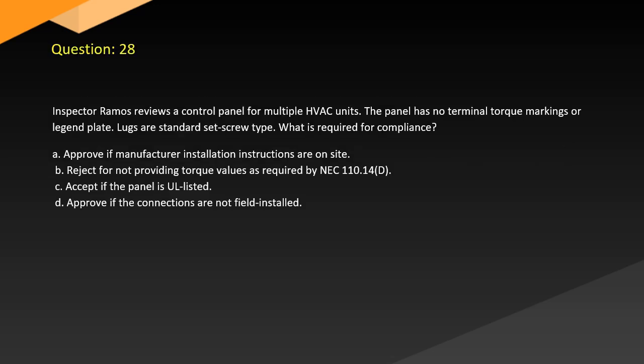Question 28. Inspector Ramos reviews a control panel for multiple HVAC units. The panel has no terminal torque markings or legend plate. Lugs are standard set screw type. What is required for compliance? A. Approve if manufacturer installation instructions are on site. B. Reject for not providing torque values as required by NEC 110.14(D). C. Accept if the panel is listed. D. Approve if the connections are not field installed.